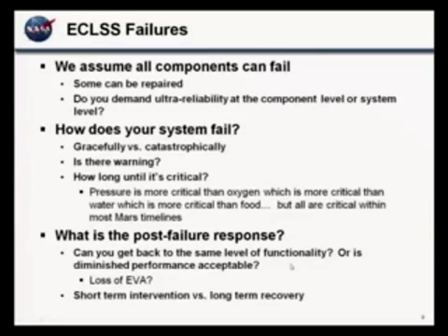If you read any of the papers on the life support system for the Orion vehicle, their CO2 scrubbing is split into three identical units that run in parallel. And they can afford to lose one of the units, and then the crew won't be able to do exercise, but can otherwise continue the mission fine. Or lose two of the units, and then you start to lose your humidity control, and the crew will survive because carbon dioxide is controlled, but they need to really restrain themselves to stay comfortable and not have humidity problems.